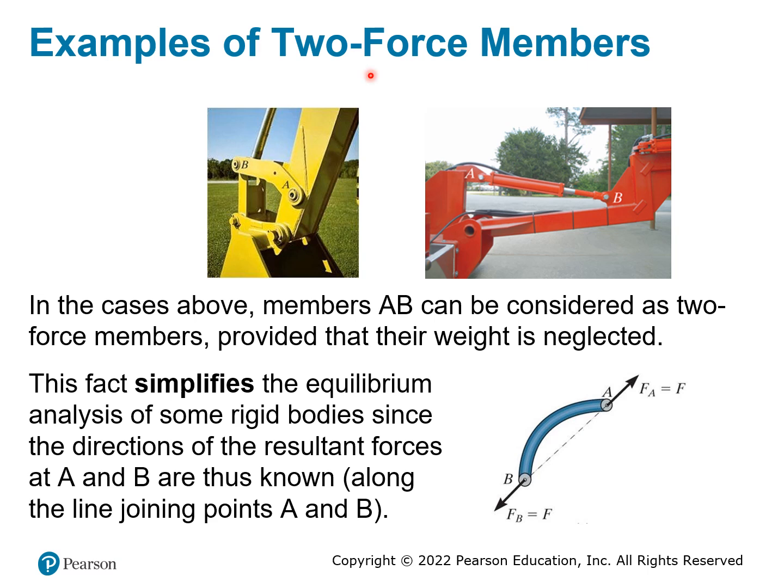Let's look at some real examples. In this yellow device, you have an angled bracket here. It has end A and end B. These 2 connect to some objects, right? So when you isolate this piece, you're going to have a reaction force at A and a reaction force at B. If this is a pin, then you're going to have a reaction force in the X direction and Y direction. Same thing over here, X direction, Y direction.